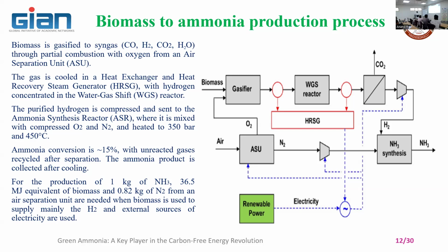Suppose you want to use the gas for engine applications, right? Then you cannot use the gas coming out from the top of the gasifier because at high temperature it has tar. When you allow the gas into the engine intake manifold, the tar is going to be deposited on the components of the engine. So you need to cool it and remove the tar from the gas before you use it.